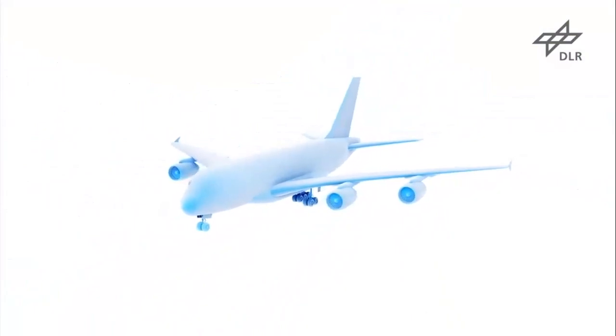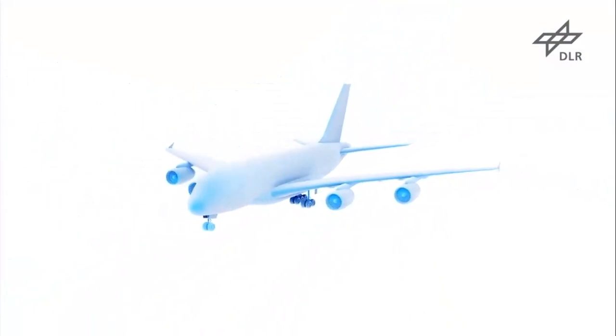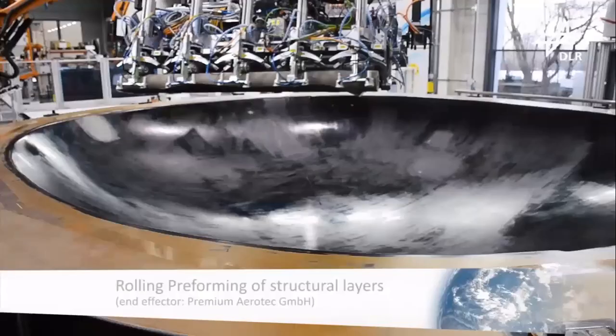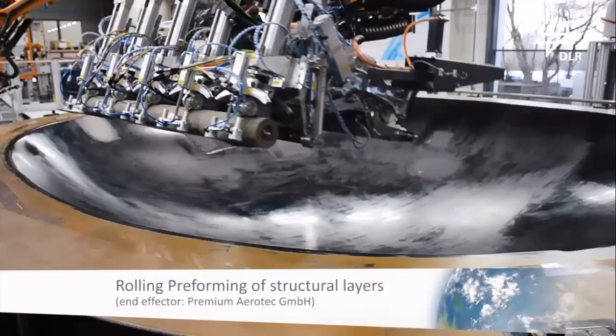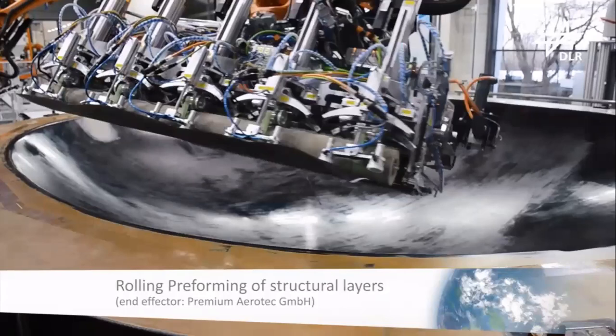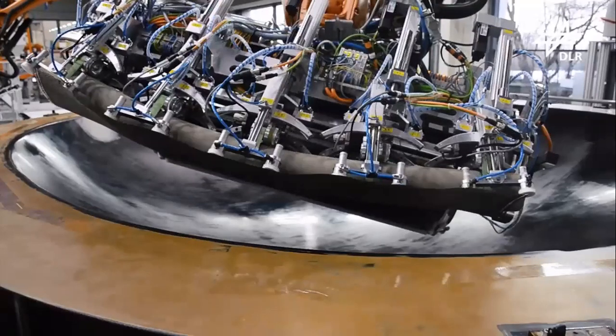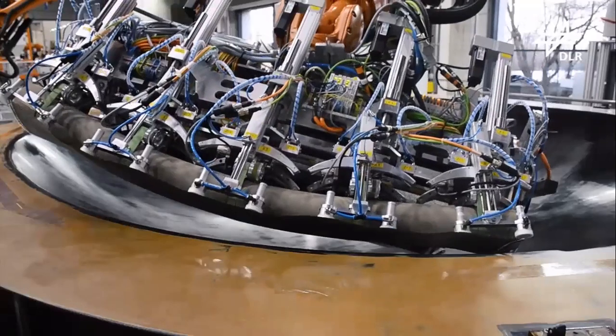During the validation phase, all sub-processes were demonstrated. The first layers of the long structural plies are placed by a rolling end effector, which applies the material directly from the material roll, draping it properly onto the double curved tool surface.